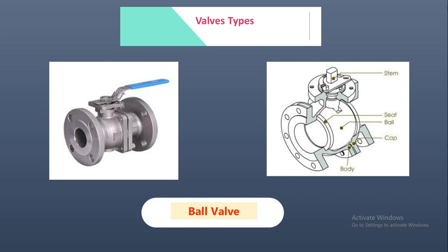The advantages of ball valves are: number one, quick to open and close. Number two, it's smaller in size than a gate valve. Number three, several designs of ball valves offer the flexibility of selection. Number four, high quality ball valves provide reliable service in high pressure and high temperature applications. And number five, force required to actuate the valve is smaller than required for a gate or a globe valve.